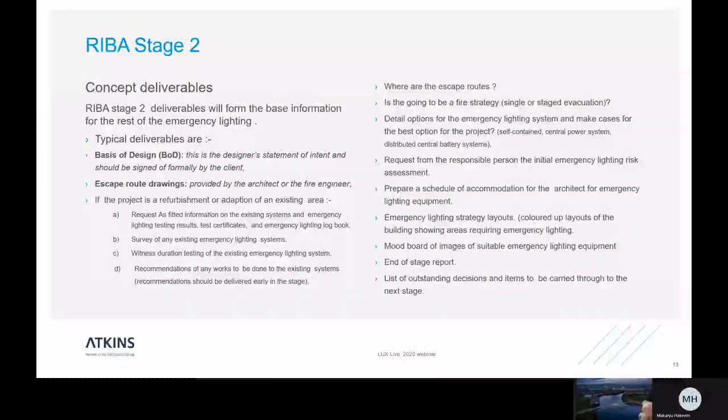So at this stage, I would also be looking to identify on a marked up drawing which emergency lighting criteria applies to each room. So is it an escape route? Is it an open area, anti-panic area? Is it a high risk area there?